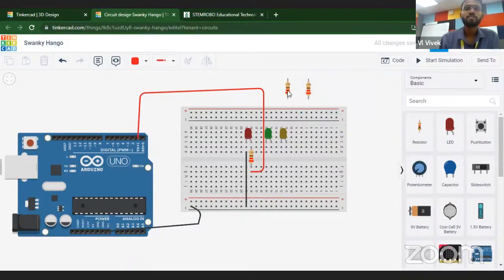Got it? Now अब मुझे बताए कोई भी, please, anyone, कि where I have to connect the resistor of LEDs, कि मुझे LED के resistor को कहाँ connect करना है? Just think about it. Positive. Okay. Could you please tell me कि क्या मैं इन LEDs के लिए एक सिंगल रजिस्टर का यूज नहीं कर सकता हूँ? Why am I taking 3 resistors on positive terminals of LEDs?